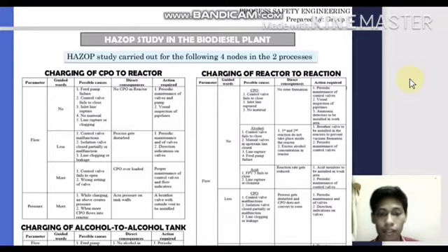In the esterification process, the alcohol that is usually used is methanol or ethanol. It is used to turn the free fatty acid into fatty acid ester. In other words, if the alcohol used in this process is methanol, the product is fatty acid methyl ester, while if the alcohol used is ethanol, the product is fatty acid ethyl ester.